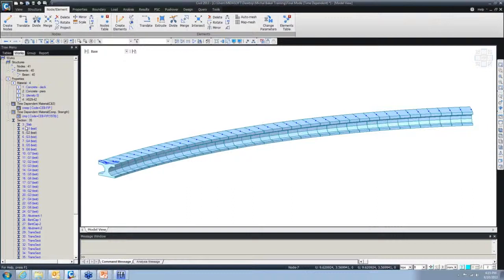Yes, they asked if we are using the grillage model, is it just a combination of some line elements or beam elements put together as the same model? Yes, it is, and it makes it so easy to do the design later on, and also so easy to extract the results on those. And as I showed you, you can simply define any tendon profile for all these girders.